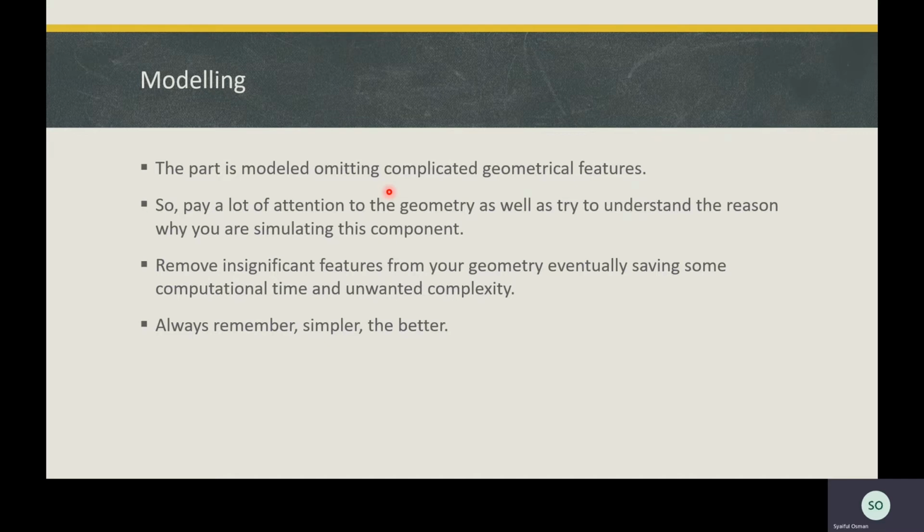Let's try to understand the reason why we are simulating the component. This will provide you the insight to remove insignificant features from your geometry, eventually saving some computational time and unwanted complexity. We need to remember that the simpler the model, the better. There is no need for unnecessary complexity when modeling your part.